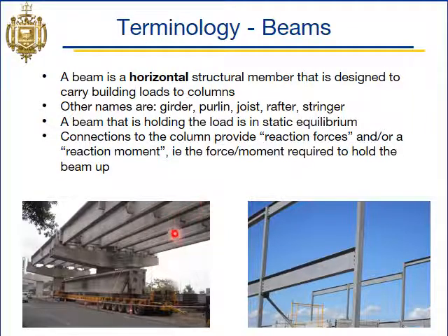So here's our pictures here. In this bridge picture, we have some large beams, right? These beams will carry the load from the cars and trucks that are above when this bridge ends up being built. And those loads will be carried over here to actually another beam, right? There's a beam across here. And then this beam will carry this down to this column here. And then this column will carry that load into the foundation system, which carries it into the ground. So beams carry the building loads essentially over to the columns, and the columns carry those down into the foundation.